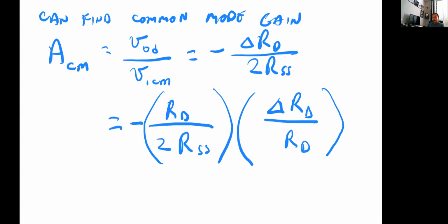And if we were going to do something for instrumentation or measurements where you can have a noisy environment and the noise is common, you want to suppress that or have a much higher differential gain for what you're measuring versus the gain of the common noise, then you would want a very high common mode rejection ratio.